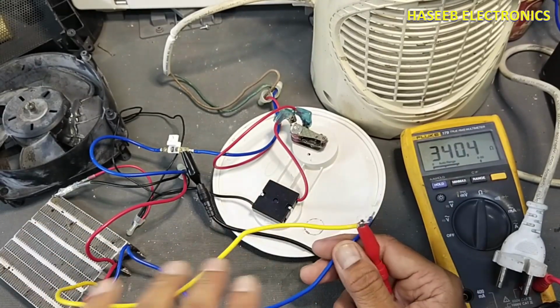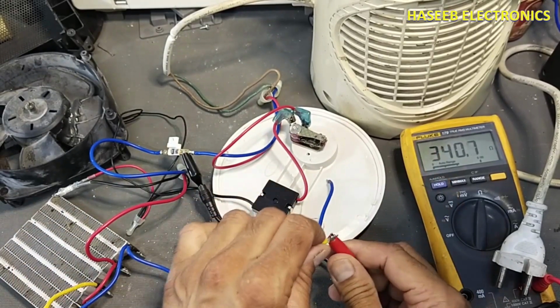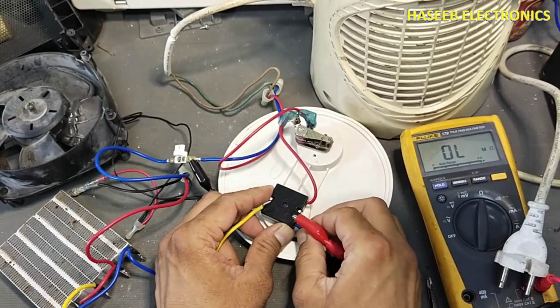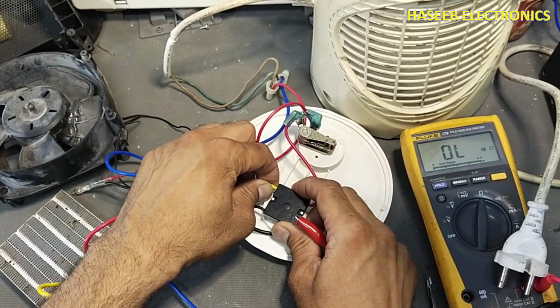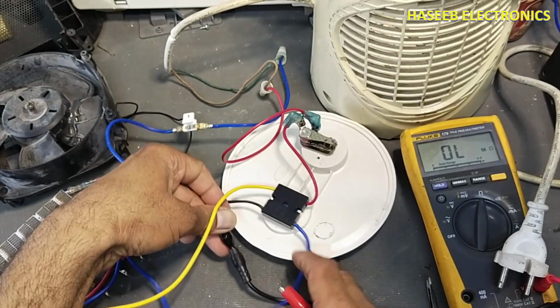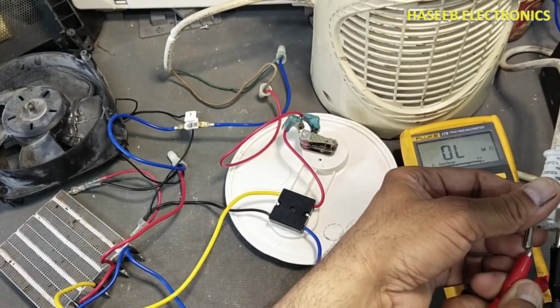When these resistors become parallel, at that time the RT will decrease. So that is the reason when this 340 ohms and 100 something come in parallel, the total resistance is reaching around 100 ohms, 120 ohms.